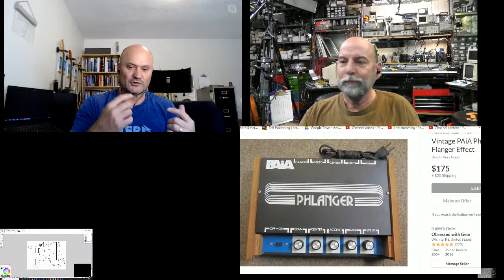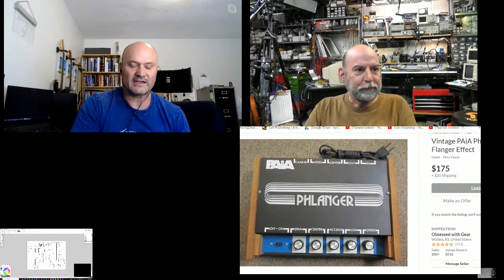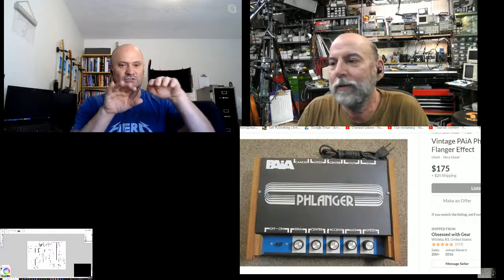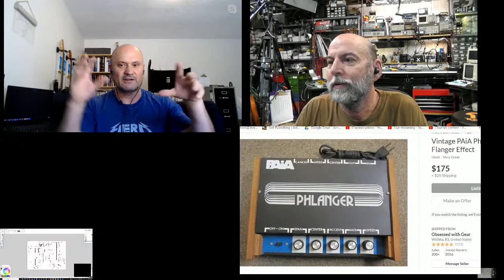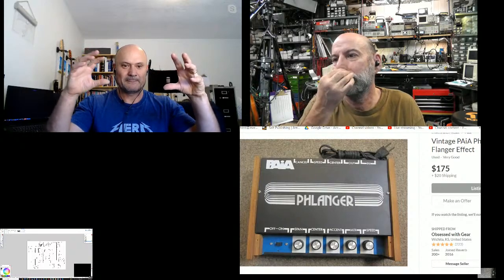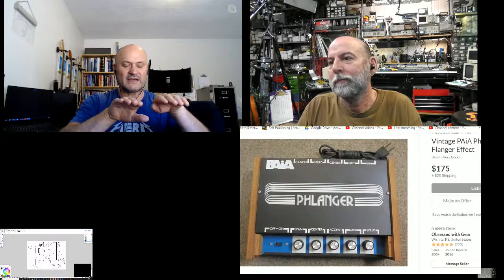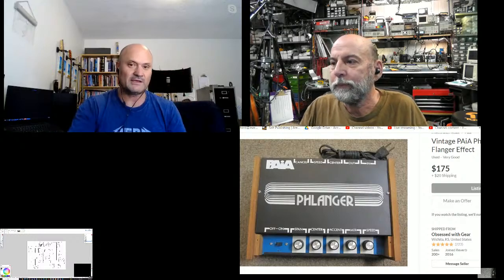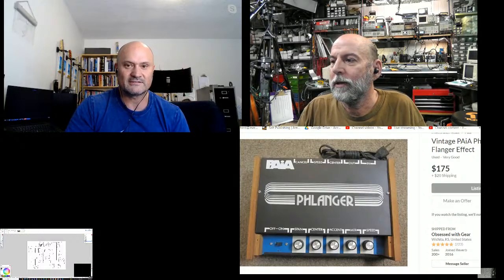But to get a true Leslie rotating speaker effect, you don't just need the pitch change. You also need two buffers for the stereo, one for each side of the horn, and you need to clock them, and the low frequency oscillators that speed their clocks have to be 180 degrees out of phase. Right.